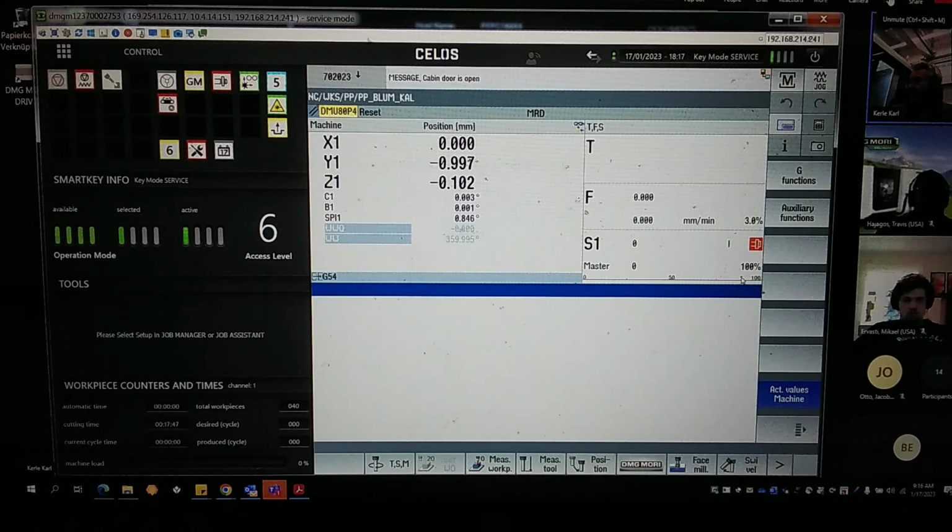Here we have a minus button, so we can go down in steps of 5% to 70, or sorry, let's say to 50. Then we have a 100% button there, and also then we have a plus button. We can increase the spindle speed until 120%. That's the range. Okay? So far so good?